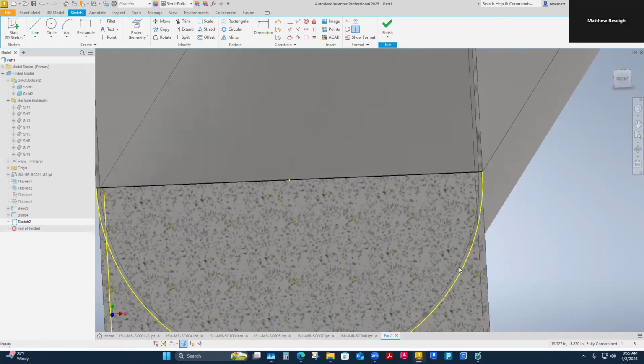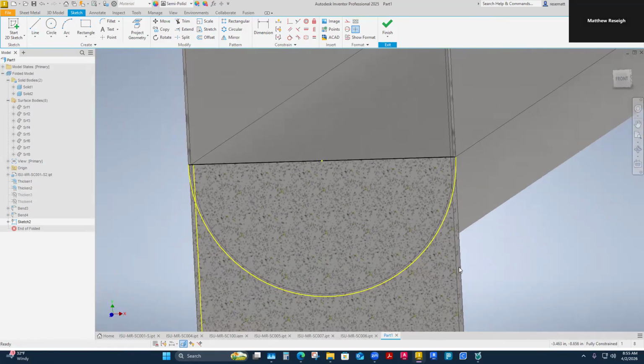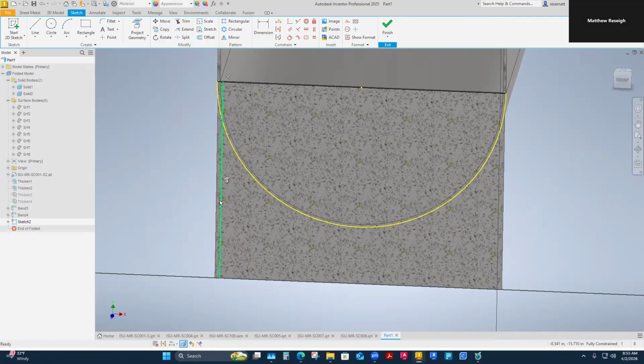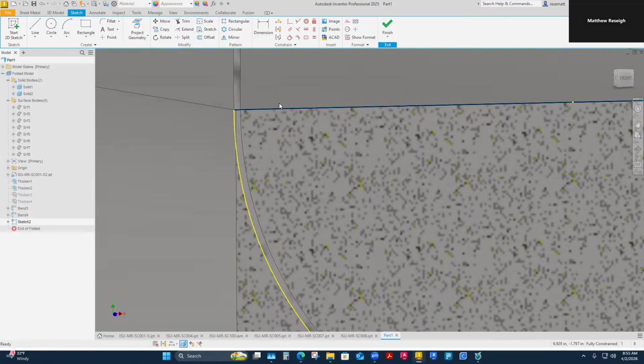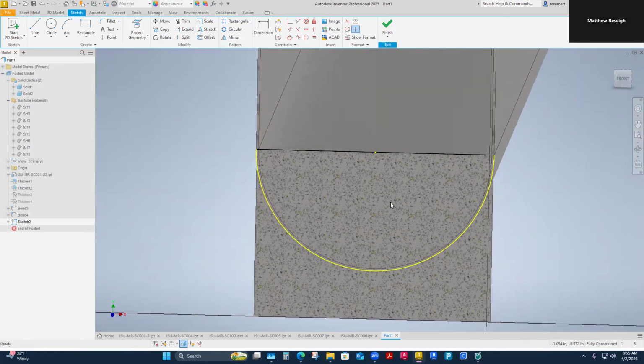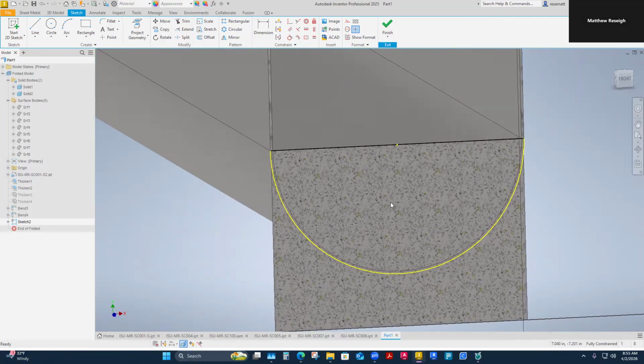And then it's constrained. So it's really not dimensionally constrained. It's just a projection. I don't think I need this one. And sometimes you'll have other projections show up. That one, for whatever reason, I got tied into. No, it's all good. Sometimes when you're drawing on that, it'll choose to project some stuff if it feels like you locked in on a point from that geometry. I try to be careful with that. I only try to project stuff that I want.